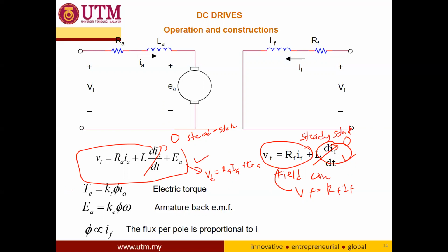And you also need to know this equation, the torque equation. This torque is proportional to the armature current. And we also need to know this equation. So there are actually 4 equations that need to be remembered in order to solve the motor drive problems.